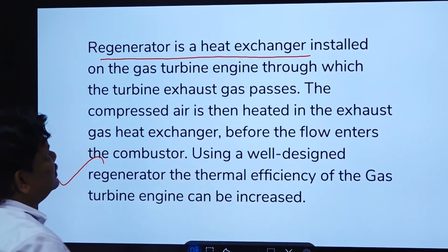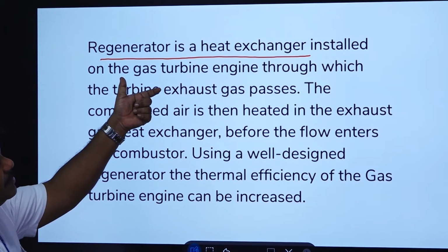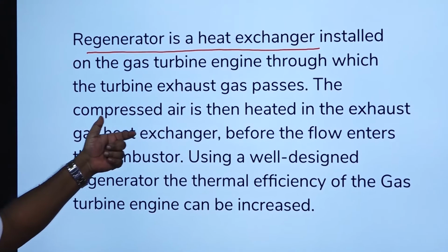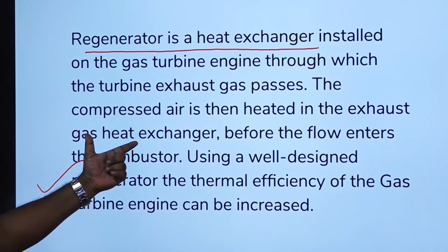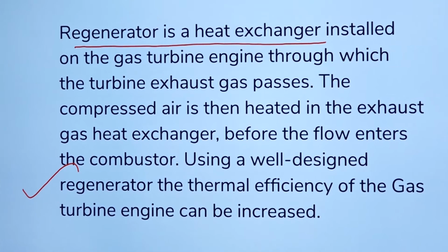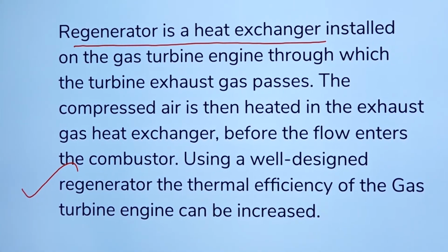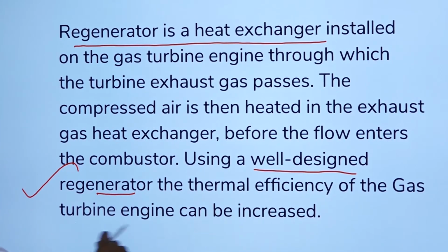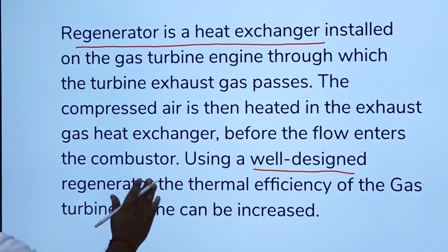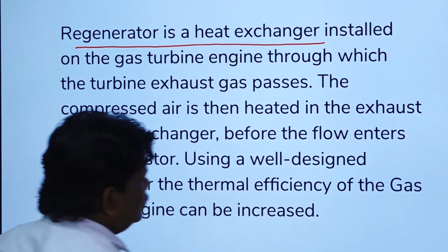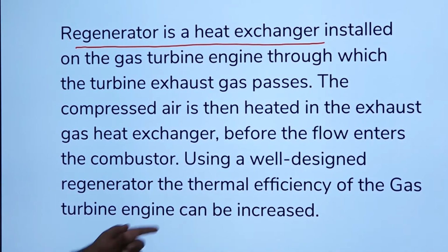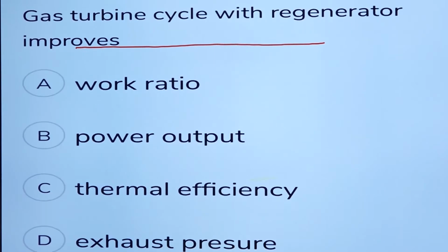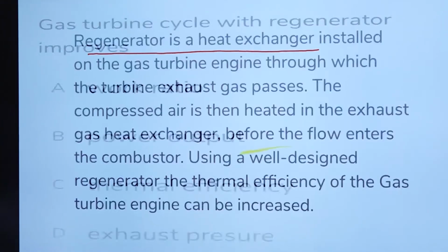It is a heat exchanger which is installed on the gas turbine engine, through which the turbine exhaust gas passes. The compressed air is then heated in the exhaust gas heat exchanger before the flow enters the combustor. So using a well-designed regenerator, the thermal efficiency of the gas turbine engine can be increased. So when you use a regenerator, the thermal efficiency of the engine increases. So for the previous question, the answer is thermal efficiency.